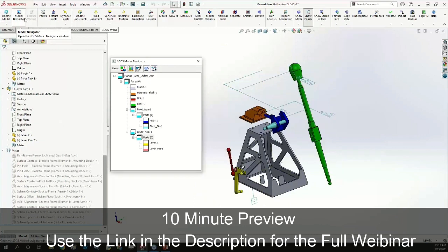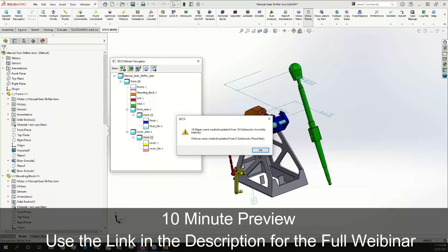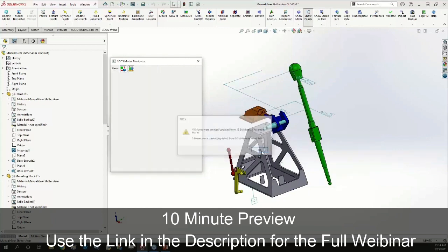And I'm going to go ahead and select this Update Constraints button right here. And this is going to be familiar to anyone who's used our Mechanical Modeler add-on before. It's just the exact same Update Constraints button and the exact same Update Constraints functionality. So I'll click Update Constraints. And then I'll select my assembly. And it'll tell me it was able to create 18 total moves based on the 18 SolidWorks mates that I had.